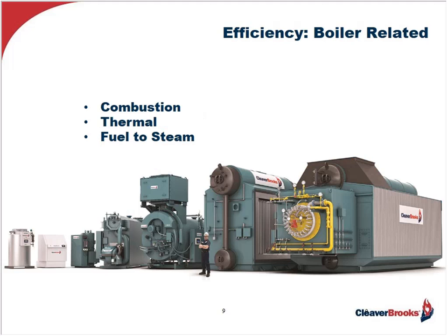The next step in the methodology is to determine the boiler's efficiency. And to do this, one needs to understand there are various terms applied to efficiency, and you need to understand the differences. For instance, sometimes combustion efficiency is used as a reflection of boiler efficiency, when actually this is really the ability of the burner to combust the fuel with the least amount of excess air as possible, without exceeding or compromising acceptable levels of carbon monoxide and, of course, safety.